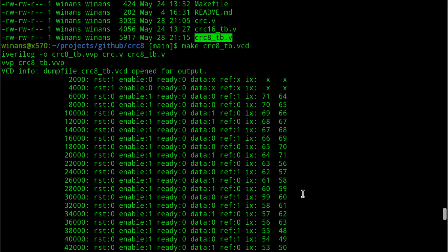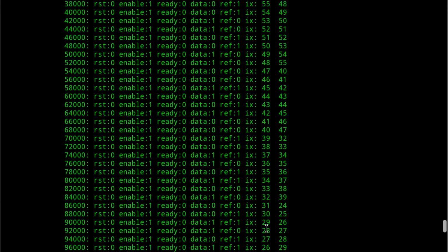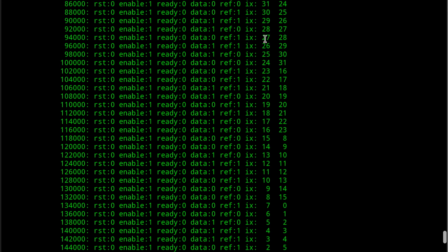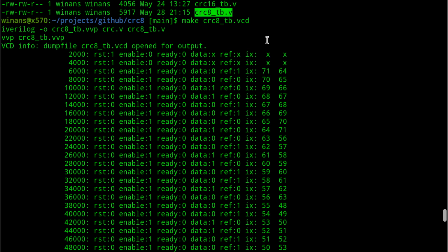If all your data bits arrive in big endian order, this is the order in which the bits will arrive, from 71 down to 0 in this order. If you choose one that's reflected and the data arrives in big endian order, then you're a dingbat, because what you'll do is you'll save up 8 bits, then you'll reverse them, then you'll apply it to your CRC calculation.